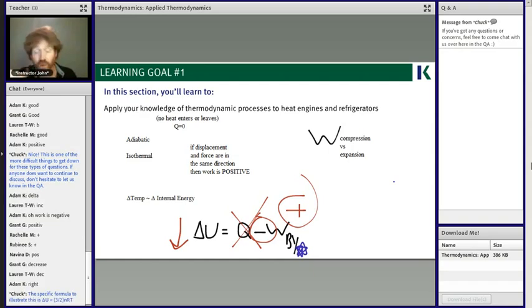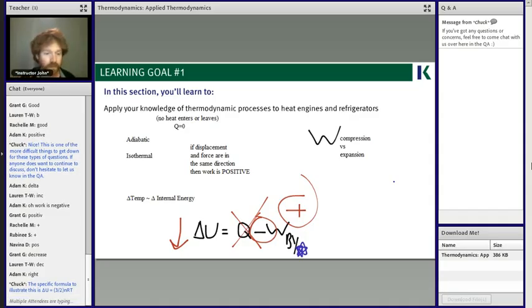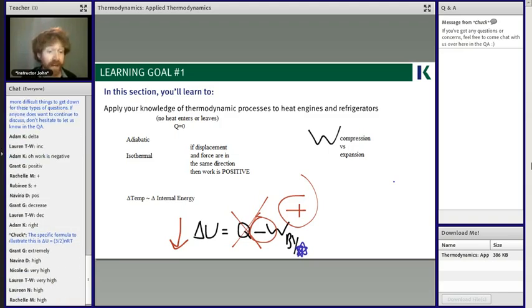Now, conceptually, and Trick's got the actual formula, think about it in terms of molecules, right? So internal energy is temperature. And internal energy is the vibrations, the oscillations, the collisions, all the movement, all the energy going on with every little gaseous particle. So if you take all the gas particles in a room and you compress them down to a tiny point, how energetic is that tiny point going to be? Very high or very low? Super high. Yeah, you take all the gas in a room and compress it down, that's like an explosive little bundle now, right? And if we're saying it's high energy, that by definition means high temperature. That's the big thing, the relationship between the two.